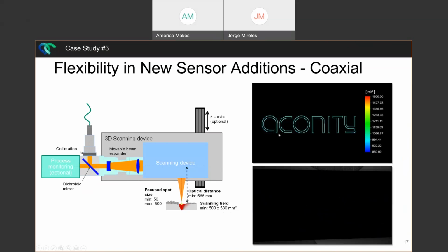And then with pyrometry, you're able to, again, coaxially measure emissions coming out. And so what this has allowed is for us to see differences in energy input, right? So if you have a complex geometry, your scan vectors are shorter in one area, longer in another, you'll see a stark difference in the energy input, right? So you'll be applying more energy in those short vectors because there's less time for energy to dissipate. But yeah, this has been a really cool option to, again, validate models. And then some people are trying to get absolute temperatures to get to that more efficient parameter development type work.